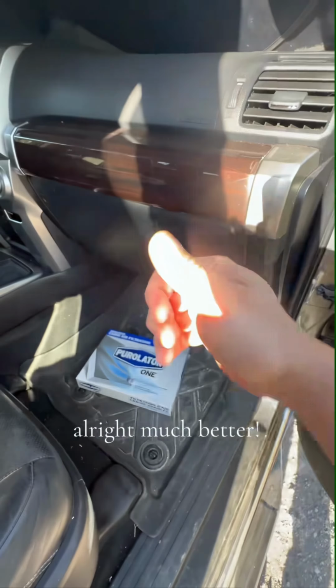All right, now we can reinstall them on the calipers, and I'm also going to make sure that the caliper pin boots are installed properly and nice and sealed. If not, dirt, debris, or water can get back inside there and wash out the grease, cause it to rust, which is the problem that we had to begin with. All right, much better. No more noises.